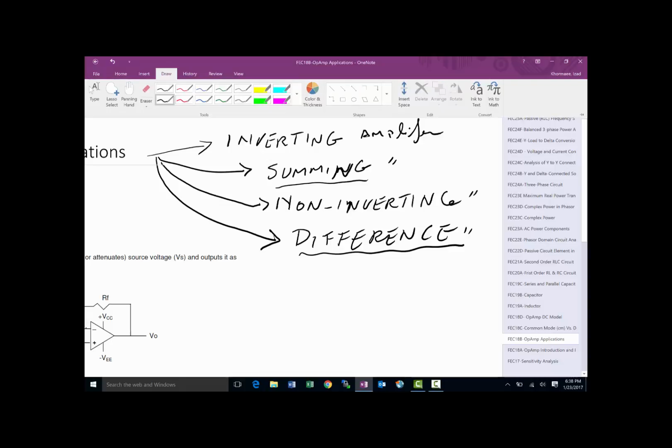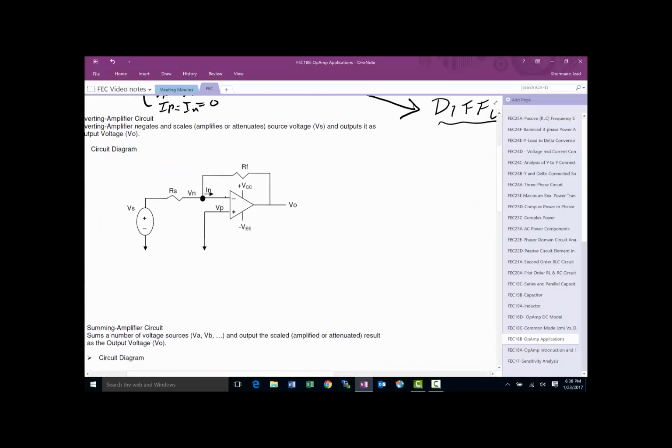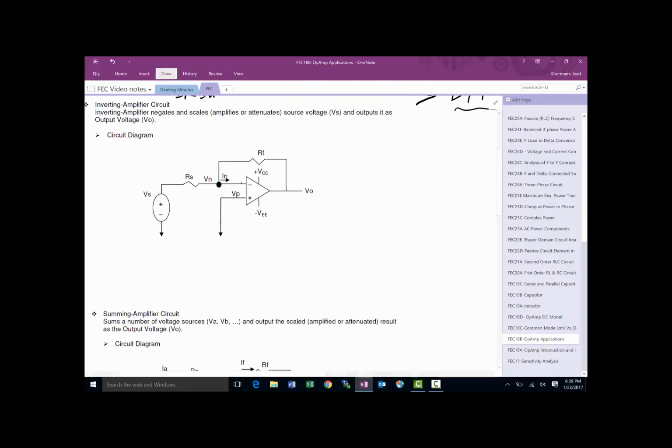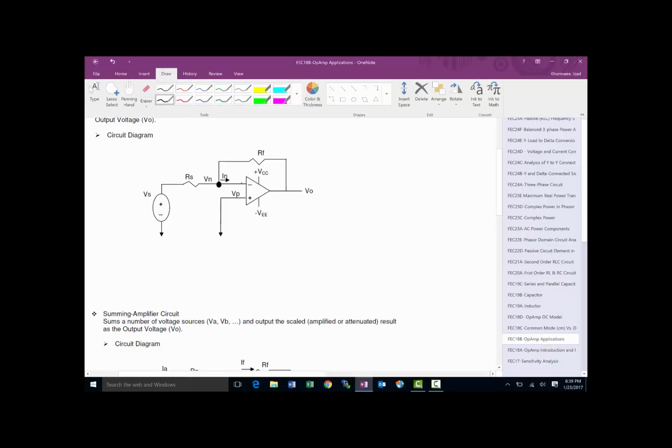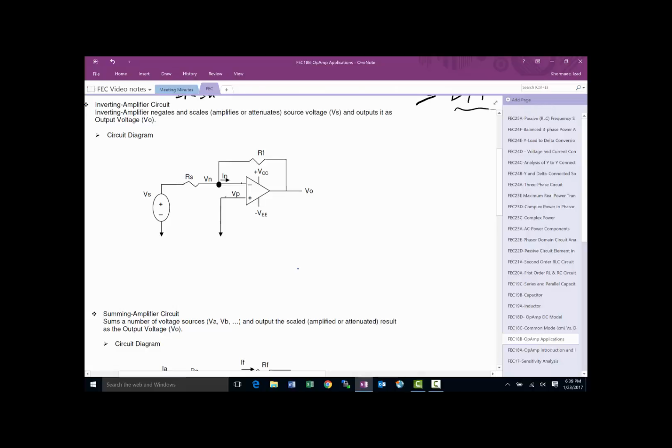Okay, so we're going to start first with the easiest one of the group, which is the inverting amplifier. And once we work out the solution, hopefully you'll see why this is called an inverting amplifier. So as we talked before, this is Vp, and Ip is going to be the current that goes in here. The easiest way to solve this problem is KCL, the node voltage method. Typically, because we don't know what Iout is and we don't really want to learn it, we don't write this particular node. And when we say Vout, we are saying Vout with respect to a reference point.